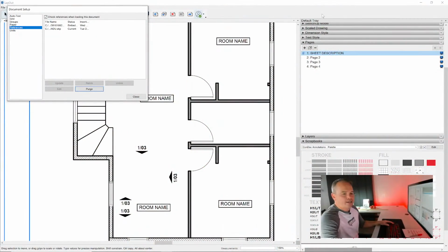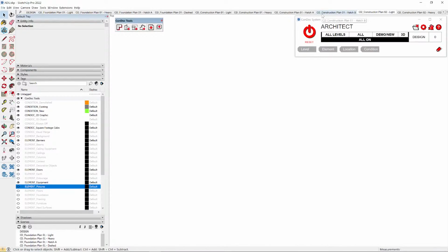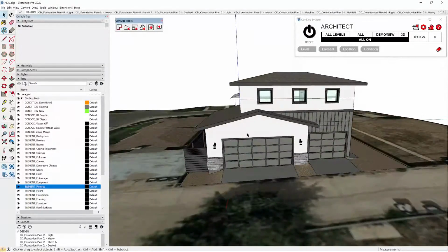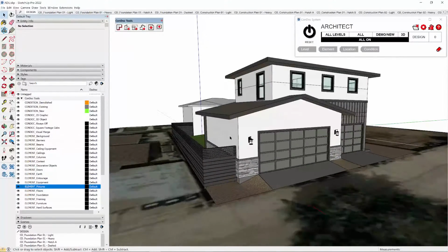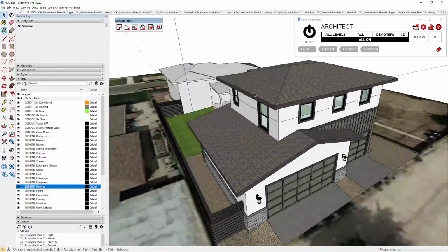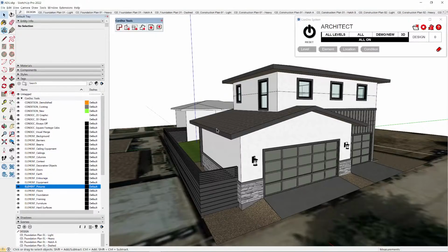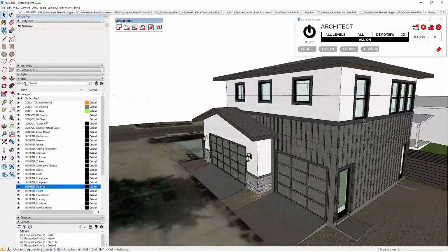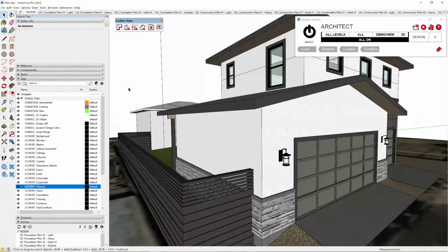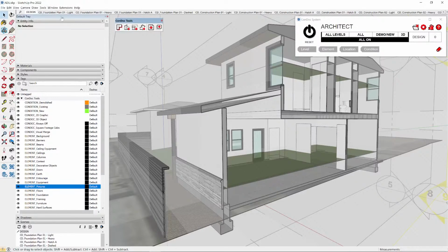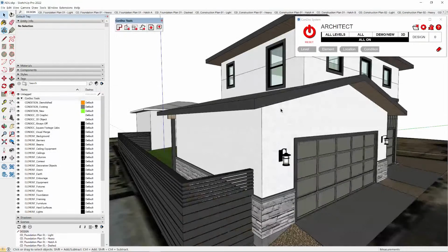All right, so then again, back into SketchUp, I'm gonna click Reset, and then I'm going to go to my section tool. Maybe this garage wall would just be a good example. This would be a good section cut. This would probably be a reasonable one, but we'll just focus on one. Activate the section tool and then click where you want to cut. Instead of giving this a fill, I just want a very simple CAD section like that. All right, and so there we go.